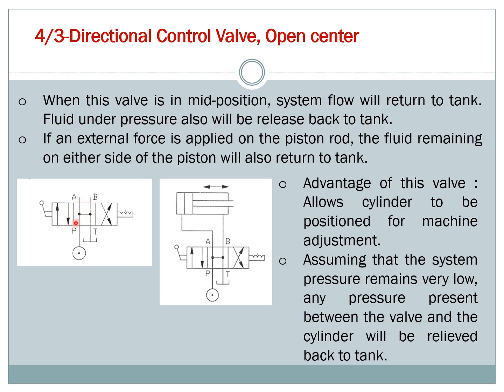If an external force is applied on the piston rod, the fluid remaining on either side of the piston will also return to tank. So this is another setup where all the excess oil will return to tank, no matter what position it is in.